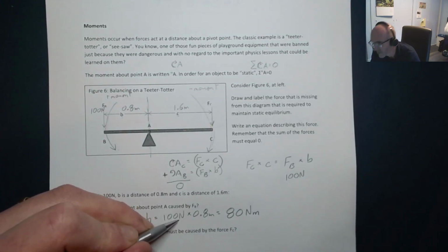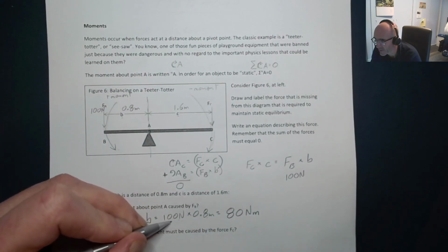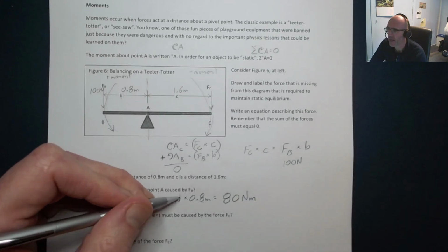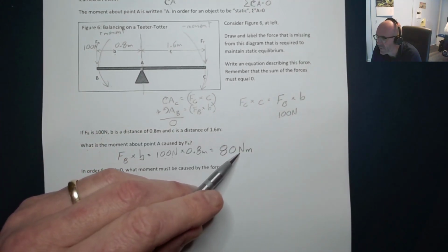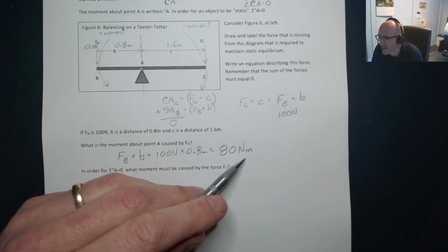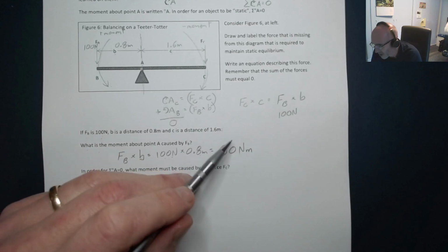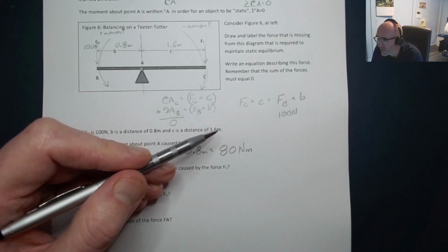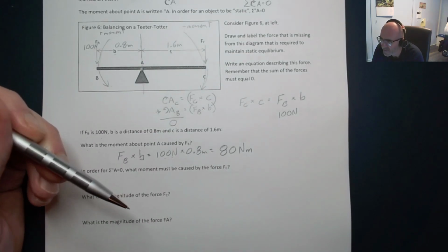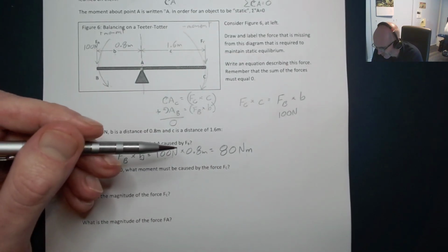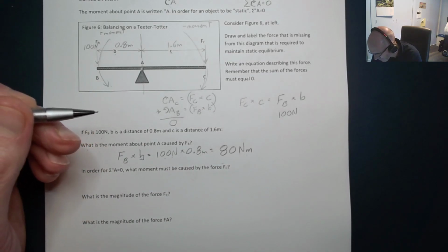And you can see here, we've just multiplied the force times the distance. Just as we do that with the number, we do that with the unit. If you've used torque wrenches or anything like that, you're probably familiar with Newton meters. 1 Newton meter would be the force of 1 Newton applied at a distance of 1 meter from the center point. 80 Newton meters, that's a pretty good torque. You're wrenching on it if you're putting 80 Newton meters onto something.